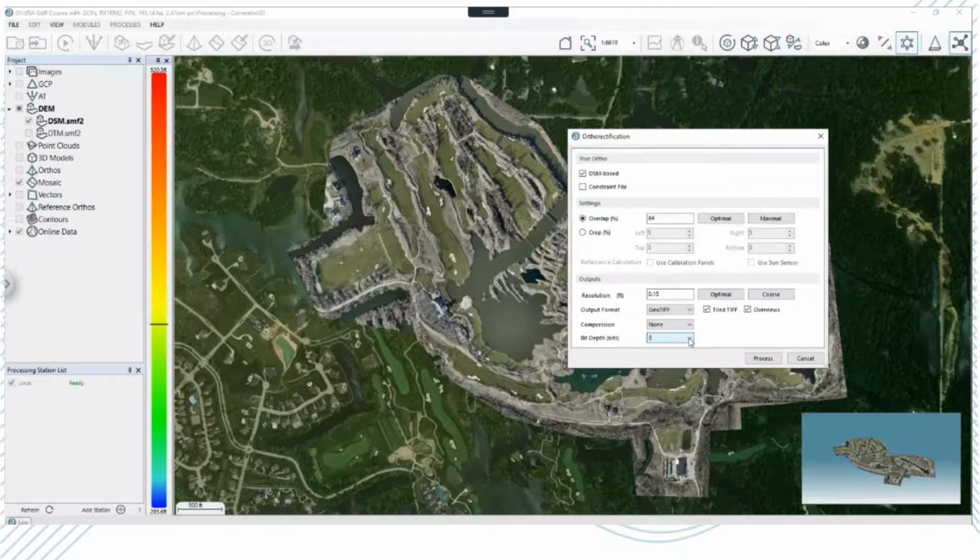That is great when you're doing the AT portion, and you get a little bit more view in the shadows and things like that when it's doing tie point adjustment. But again, is your customer on the other end using 8-bit or 16-bit? They're probably only using 8-bit. So at this point, you may want to say, let's process out in 8-bit these orthos. So that's certainly something that we needed to bring up.